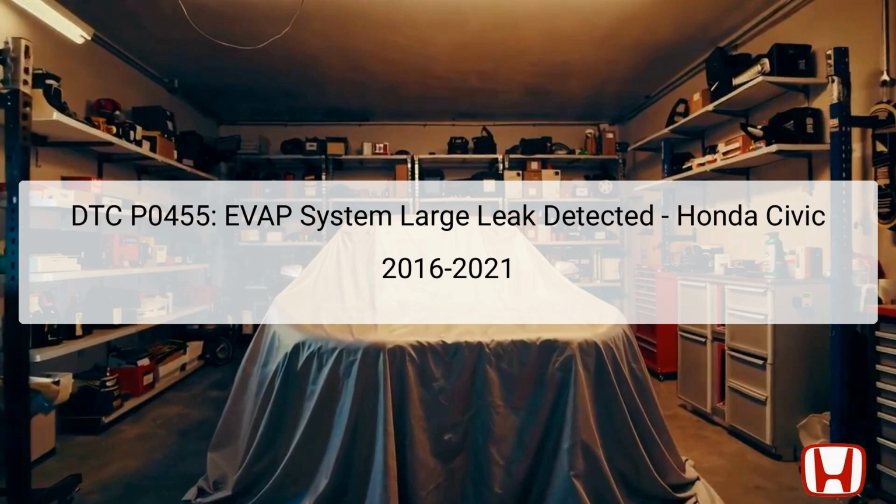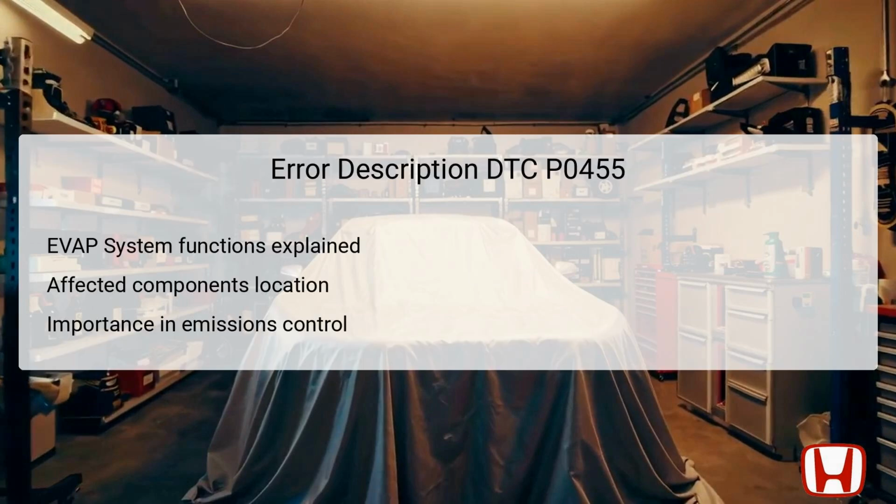These parts are crucial for controlling fuel vapor emissions and maintaining the appropriate conditions within the system. They are primarily located in the engine compartment, fuel tank area, and the chassis. Properly diagnosing and fixing this error is essential to ensure that your vehicle is not only functioning optimally, but also environmentally compliant. The DTC P0455 error code specifies that the vehicle's EVAP system has detected a large leak.